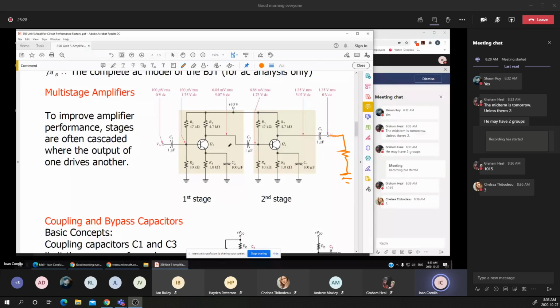Suppose that I'm not having this capacitor connected between the two stages. You notice that the Q point on the first stage is affected by connecting the other resistance or the other circuit on the collector of the first stage. And that's why we are not using a direct connection between, for example, the collector and the load. Again, I make the same assumption that C5 is not present in the circuit.